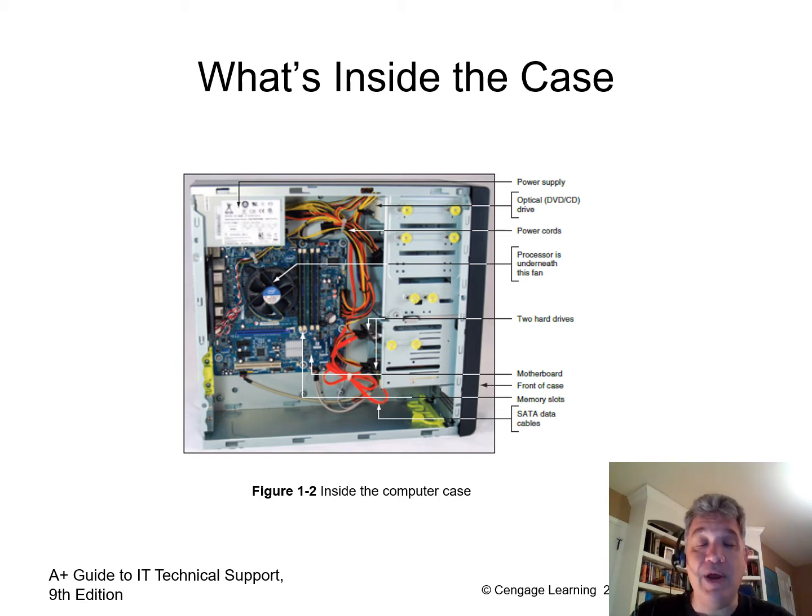I would highly recommend that if you're going to do something like that you do it outside. Also, it's not a good idea to use a vacuum in close proximity to the PC, because the vacuum can generate an electric charge, and even if you don't feel the discharge, you can cause damage to other components. So resist the urge to use a vacuum around the PCs and for that matter laptops in favor of compressed air.